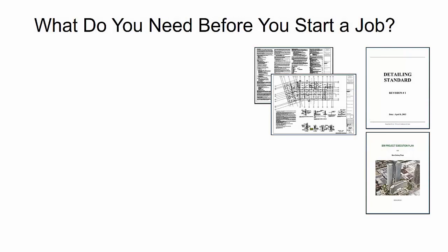So let's go ahead and do a recap of the things that we need to start up a project. First, we need the design drawings. Most definitely the structural drawings, because that encompasses the scope of what we're typically detailing. And then oftentimes we need the architectural drawings to verify dimensions and additional information that coordinates with the structural. Or if you're doing a miscellaneous steel detailing project such as stairs or other miscellaneous iron and steel, then the architectural drawings will oftentimes supply some of that information.